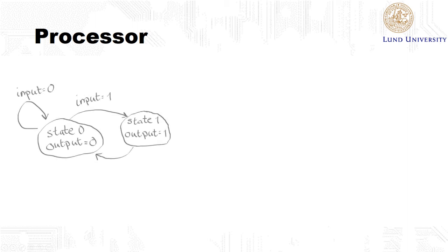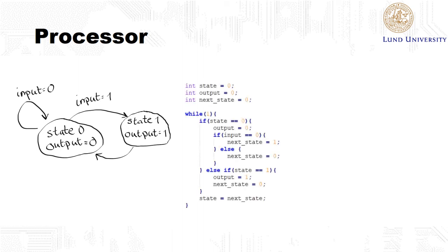Lastly, it is also possible to implement some digital system in ordinary software by writing a program, which is then executed by the processor or a more specialized digital signal processor. However, every execution step is controlled by the system clock, and thus it is not possible to implement combinational circuits. The benefit of using a processor is that it is quite easy and quick to implement, for example, a finite state machine in a high-level programming language. But it might be hard to control the timing of signals, as the number of clock cycles needed to execute a single line of high-level code may vary.